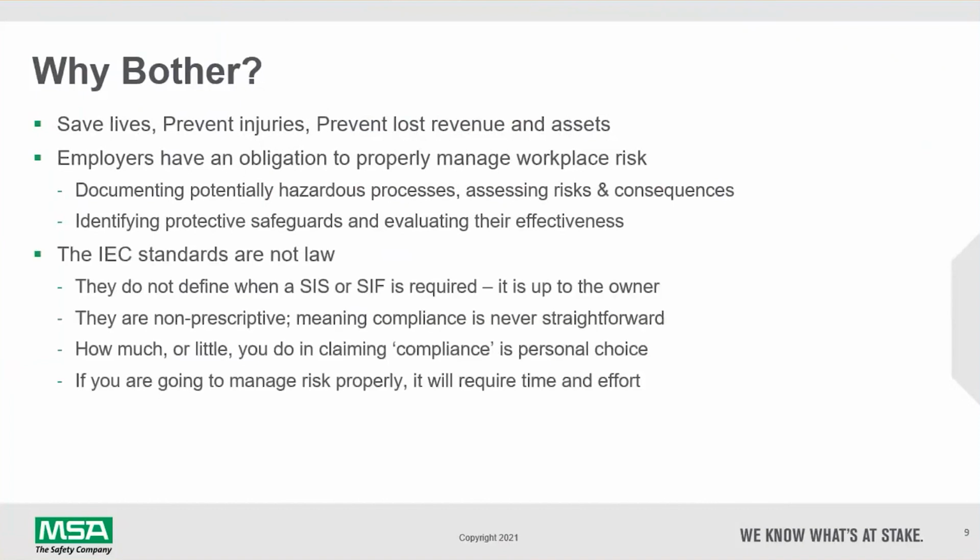But to be clear, these standards are not law. So they don't define when a safety instrumented system or function is required. It is up to the owner. And since the standards are non-prescriptive, it means compliance is never going to be just straightforward and easy, if you will. So how much or little you do in claiming compliance to the standard, it is a personal or organizational choice. At the end of it all, if you are going to manage the risk properly, it will require some time and some effort.